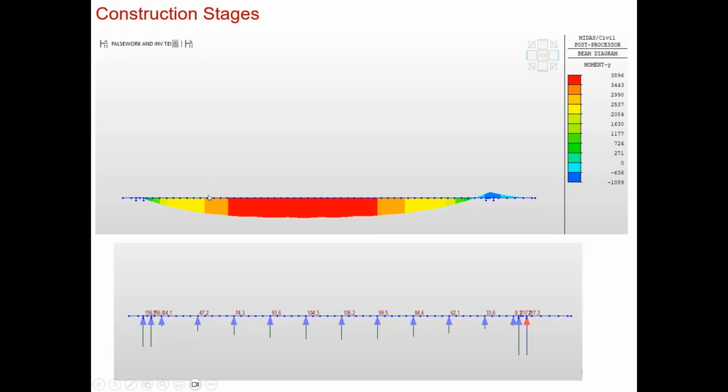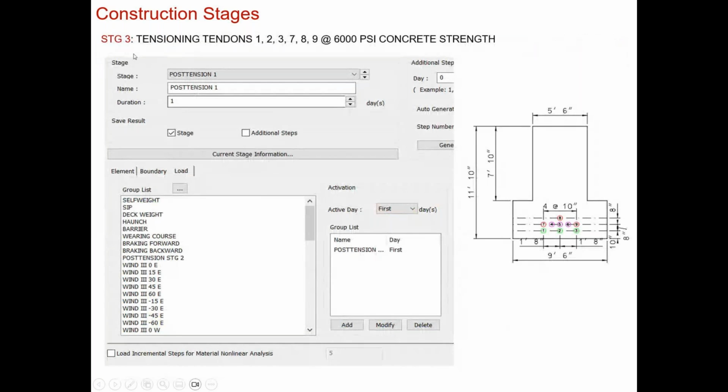And if you want to look at what's going to happen at this particular stage, you will end up seeing some bending moment on the inverted T, even though it's cast on the formwork, because it is sitting on rubber or compression-only linear springs here, which develop reactions. So this puts a little bit of bending moment on the girder, but that's not, of course, the full effect from the self-weight. And you still see some reactions going at the two ends to the jacks as well.